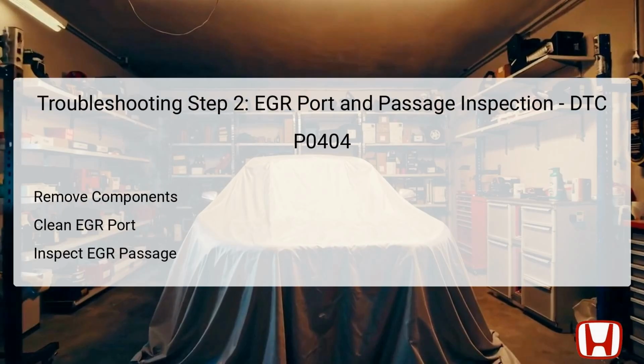For the next step, focus on inspecting the EGR port and passage. Begin by carefully removing components associated with the EGR passage, ensuring to follow the manufacturer's guidelines to avoid damaging any parts. Once the components are removed, use throttle plate cleaner to thoroughly clean both the EGR port and passage. This cleaning process will help eliminate any dust or blockage that may hinder the proper functioning of the EGR system.